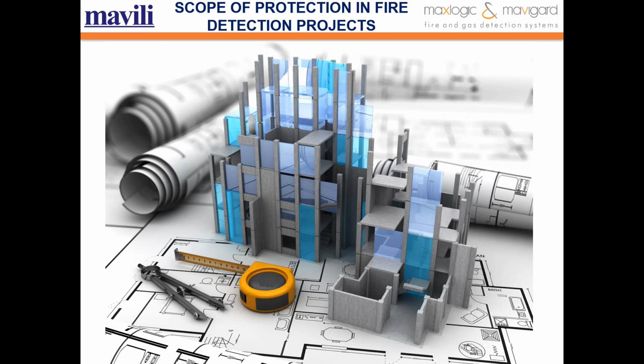The first step in designing a fire detection and alarm system in the building you are designing should be to assess the need for early fire detection in the building. In this context, we will first examine the determining factors by considering the provisions of the EN 54 standard for the protection of certain parts or the whole building.